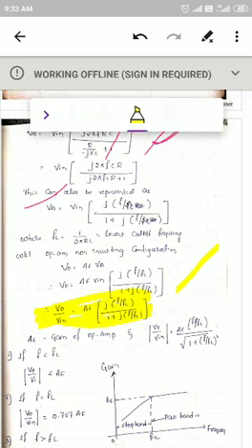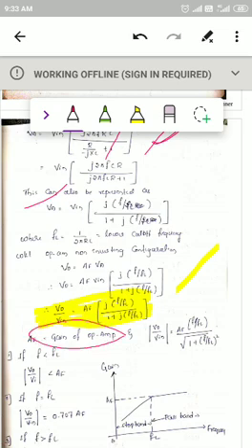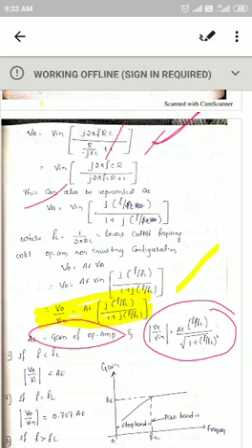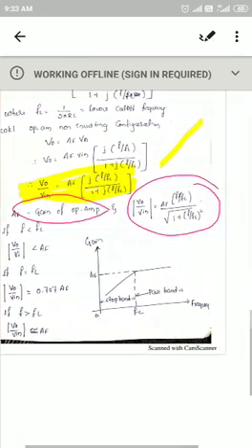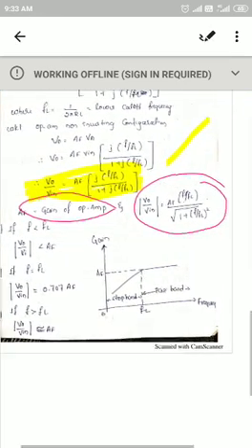If you calculate the magnitude of the gain, where Af is the gain of the op-amp, to eliminate the imaginary terms, the magnitude of Vo by Vin is equal to Af into bracket of f divided by fL, whole divided by square root of 1 plus f divided by fL squared. This is the magnitude of gain of the first order high pass Butterworth filter.